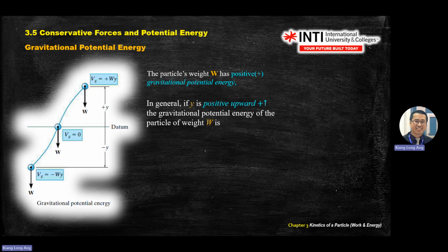Okay. In statics, we're not that tricky, but when it comes to engineering dynamics, it will be very tricky to test your understanding, especially when it comes to datum. So when you put your object above the datum before start, you get positive mgh. On the datum, you get 0. Below the datum, you get negative. So in your calculation, positive and negative are important because you're dealing with vectors, with direction.